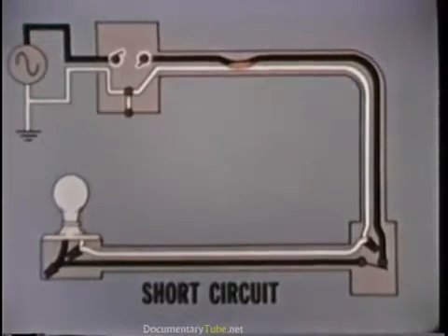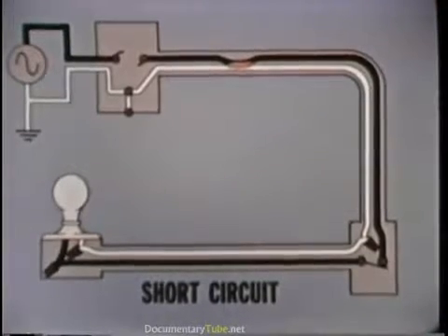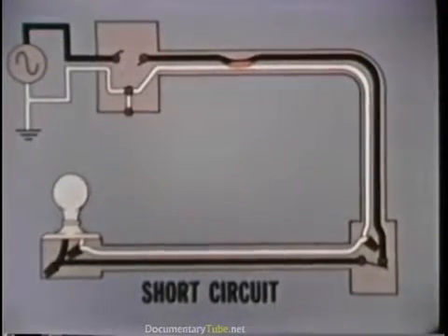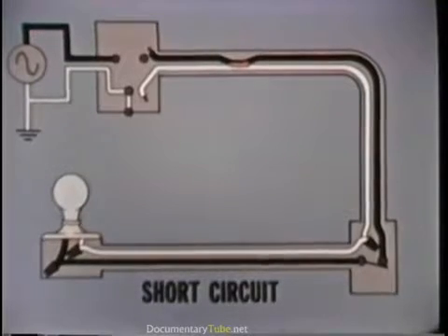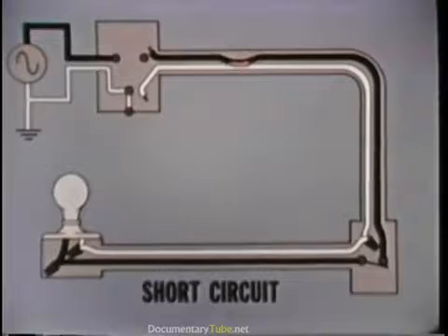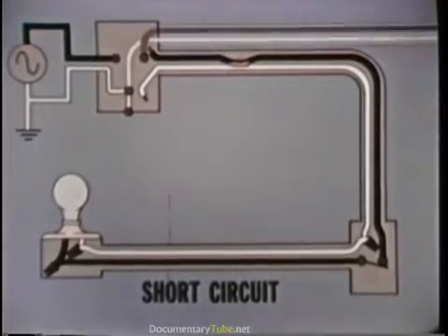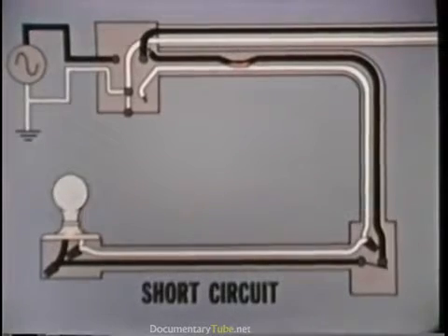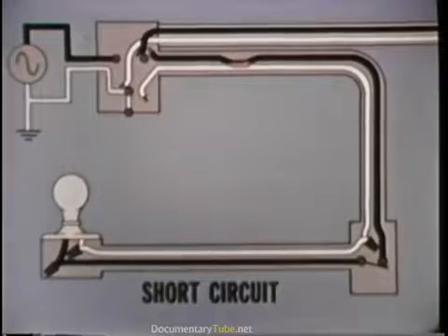The protective device has been set off, indicating that the fault is probably a short circuit or a grounded circuit. To check the wiring safely, disconnect the conductors from the power panel. For the hot conductor, this is normally done by removing the fuse or opening the circuit breaker. However, if more than one circuit is controlled by the fuse or breaker, the conductors must be physically removed from the power connection and separated.